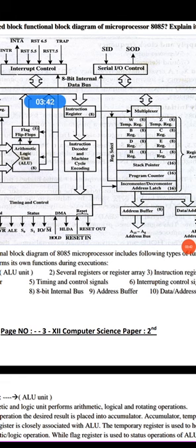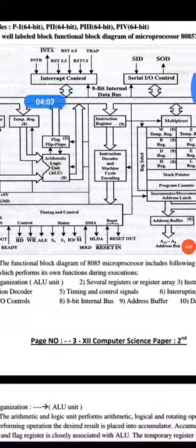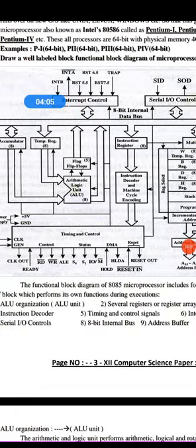Then we see another register called the instruction register, which is a very important register because the opcode of the instruction is stored in the instruction register, which is then passed to a decoder and machine cycle encoder, which is connected with the control section from which that instruction is actually executed. The last but not least register in this series is the flag register.